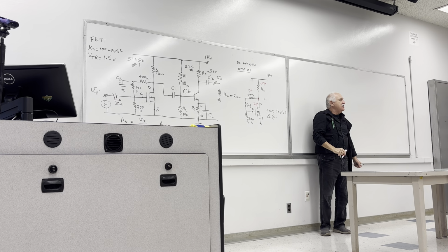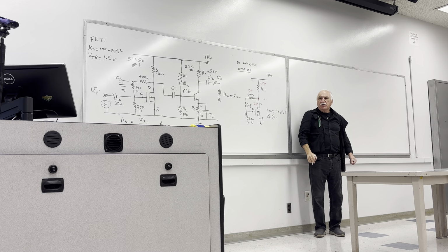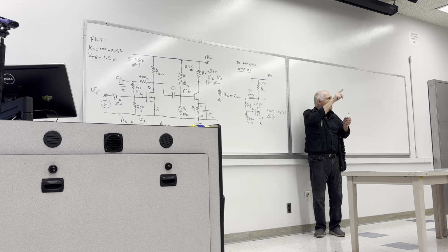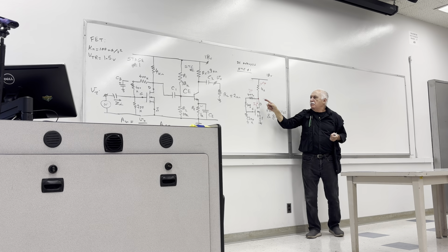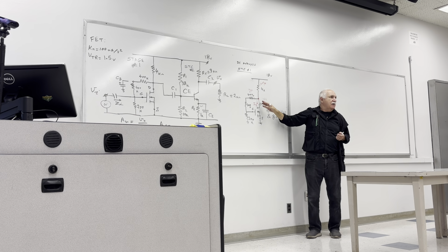I'm going to write the nodal equation at this point. You learn that according to the number of the branches, you take voltage of that node minus the other one and the other one and the other one, you divide by the resistances, right? But look at here. If I take this voltage minus that voltage divided by 4K, I'll get something like 2000 microamp.